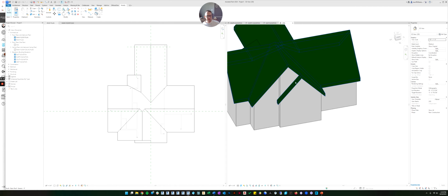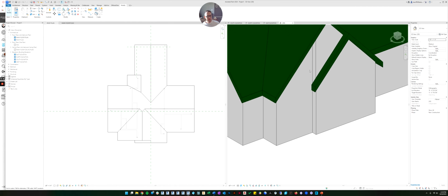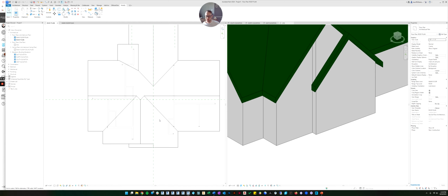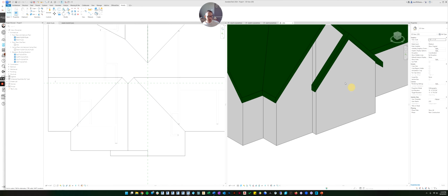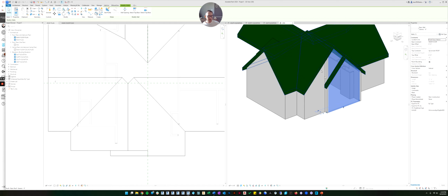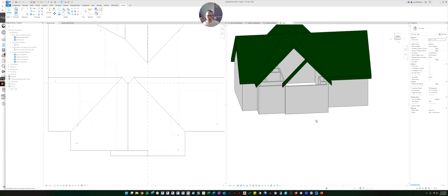First thing we need to do is create another roof that goes back behind above this wall. So to do that, really quickly, I'm going to unjoin these walls because they're not quite right. So I'm going to select all the walls, and there is a detach command. Next to the attach command, we can detach it. So let's hit detach, and we'll click our roof again, and it'll take the walls back to the way they were.